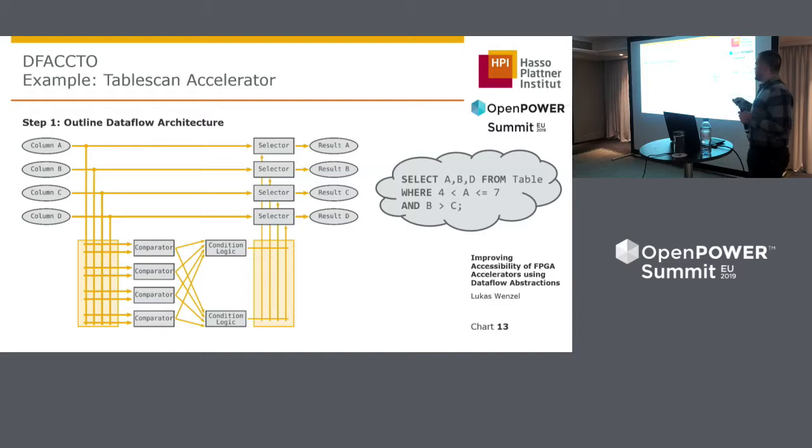Right. The design that we came up with for this is just an instance. You can design anything you want, but in this case, we are limiting ourselves to at most 4 columns per query. We can do different trade-offs, but for this use case, we just chose it. And those columns appear in 2 different places in the query, so they also have 2 different paths to travel through our accelerator. Appearing on the output side of the query, we have these straight paths going to the result columns. They pass through selectors, which just either pass on a stream element or discard it.